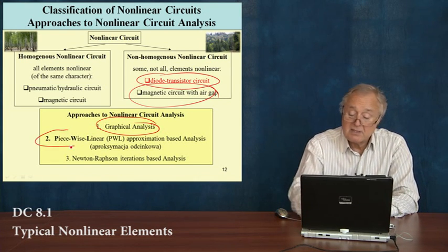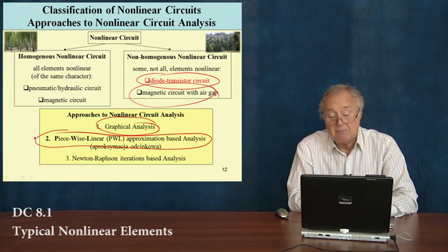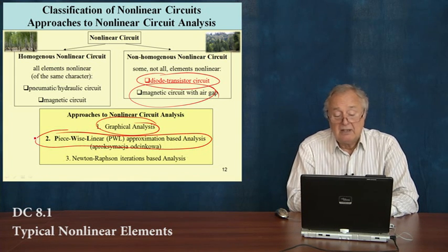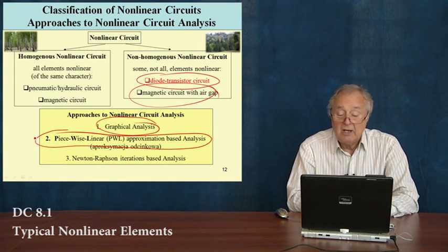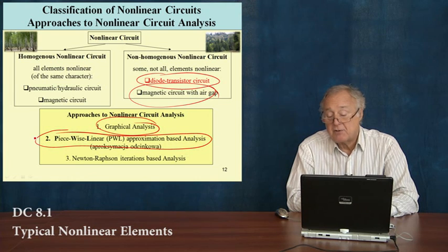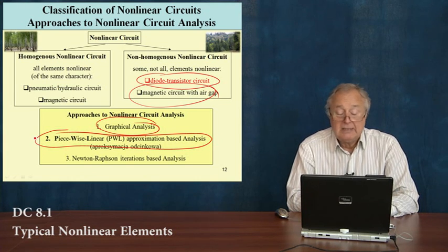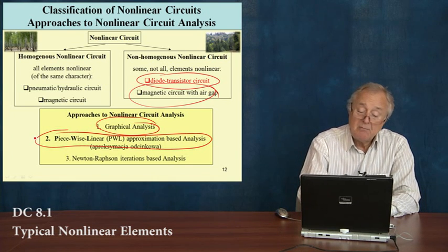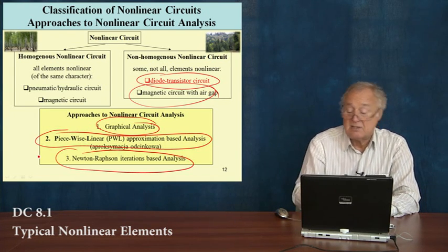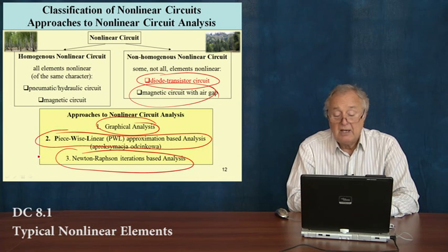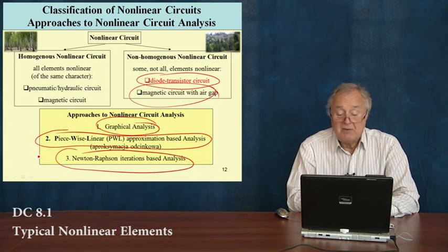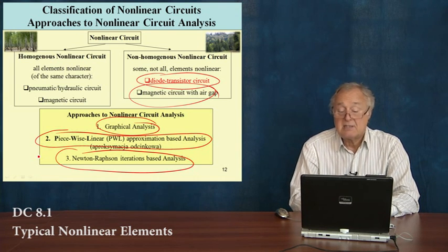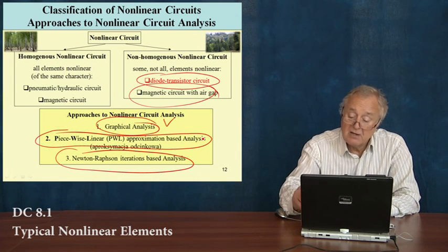Then for more complex circuits, but still quite simple, let's say 10, maybe 20 elements, not more, we may apply a piecewise linear approximation-based approach, metoda aproksymacji odcinkowej. And the method which is commonly used in simulators, in PSpice for example, is the iteration-based method, Newton-Raphson iterations-based analysis.